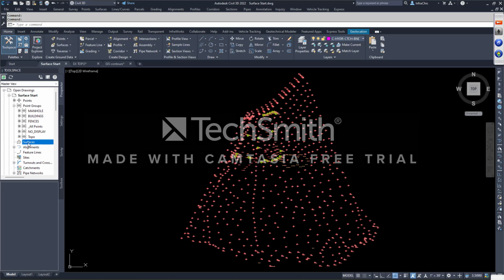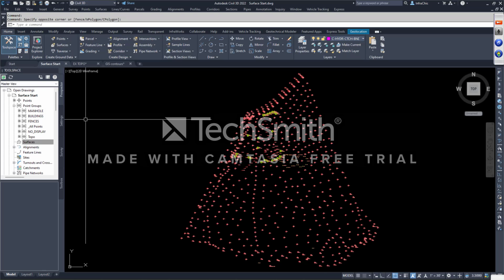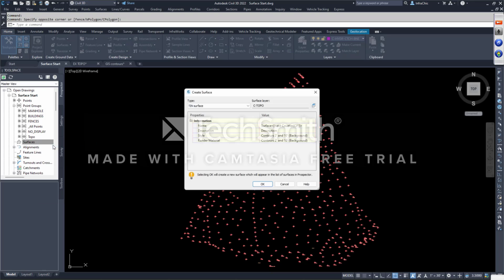To create the surface object, there's one of 52 different ways to get there. You can right-click from Tool Space in the Prospector tab over the Surfaces collection and tell it to create a surface. Or you can go up to the Tool Space, Home tab, create ground data panel, Surfaces dropdown, create a surface. So many options, right? We're going to go from the Tool Space because it's much faster. Right-click and say Create Surface.